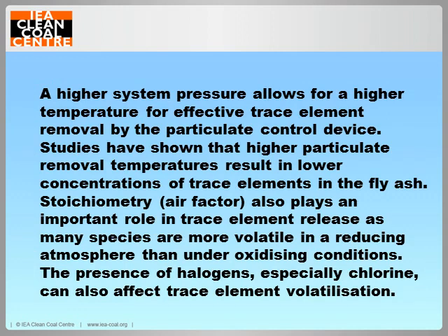Data indicate that temperature and not particle size dictates whether a certain trace element or trace element compound is volatile. For example, due to the lower temperatures in pressurized fluidized bed combustion and integrated gasification combined cycle, fewer trace elements are released compared to pulverized coal combustion, while a higher system pressure allows for a higher temperature for effective trace element removal by the particulate control device. Studies have shown that higher particulate removal temperatures result in lower concentration of trace elements in the fly ash.